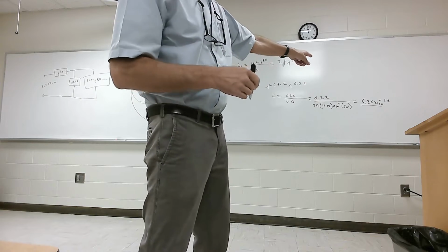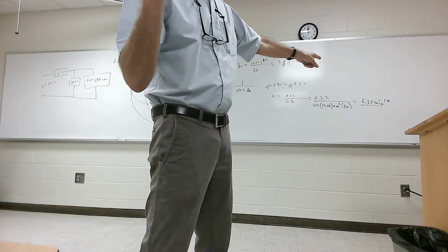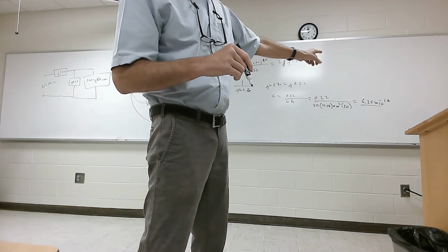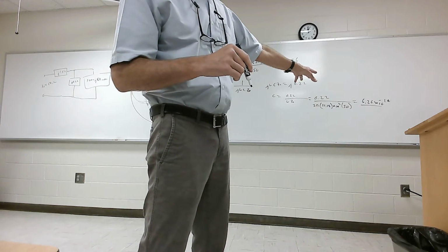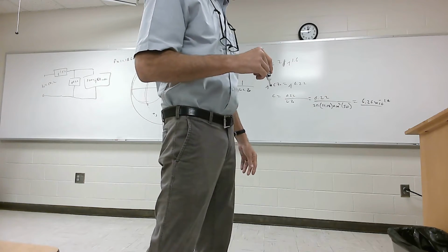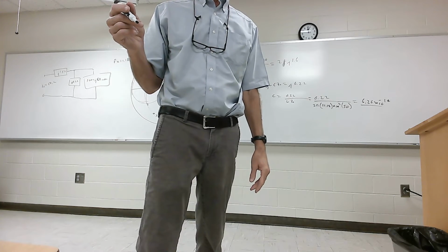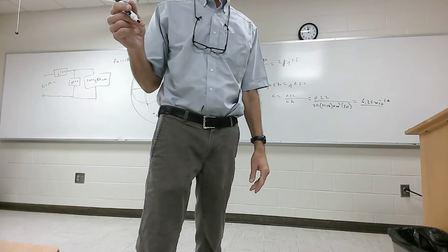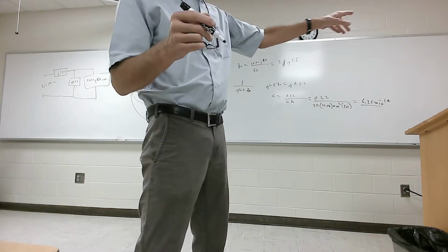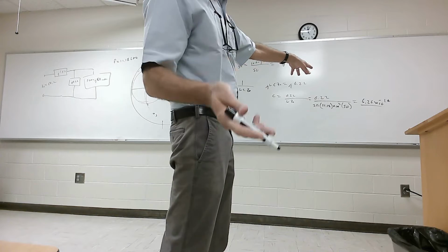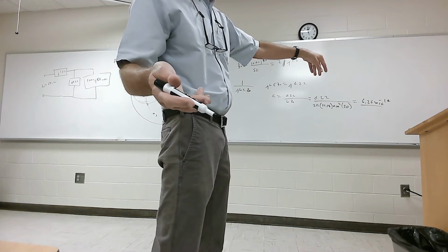By the way, you see that value? That's not realizable. That is so small. When you're talking about stuff that is hundredths of a picofarad, all right? Forget that. You're not going to have a capacitor like that. You've got to do something else with matching. And that comes later. But now, that would be the right value if you were going to do L-section matching for that.